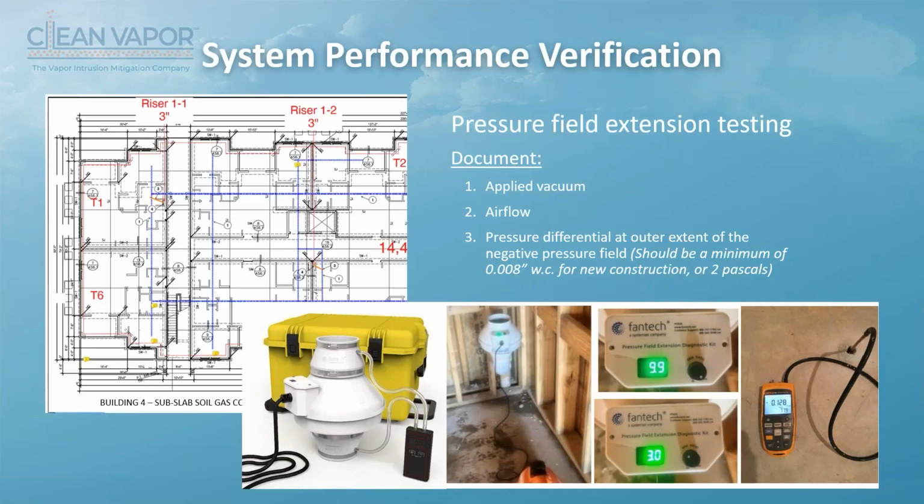Now, once it's all done and the slab is poured, you're going to want to performance test this. You're going to want to have a record of what you designed actually functions. There are some kits out there made by companies like Fantech, or you can do it yourself. You place a blower on the pipe, you measure the vacuum that's applied, you measure the outflow of air, and you measure the pressure differential.